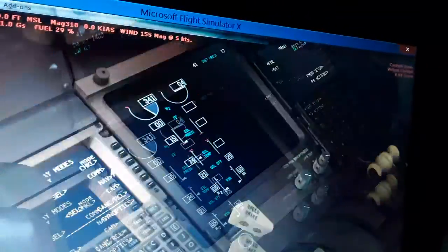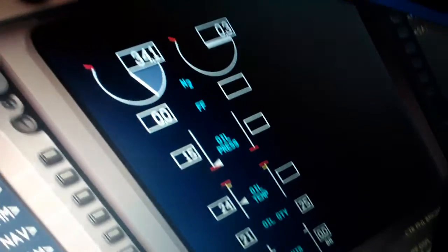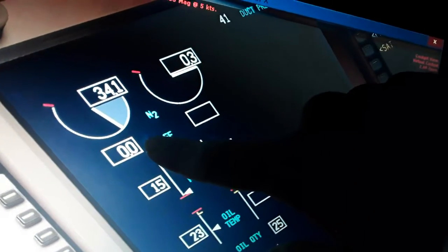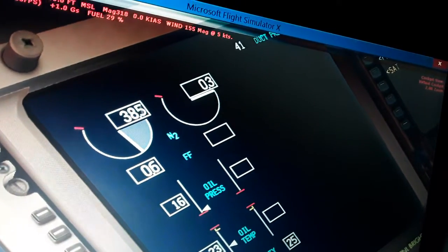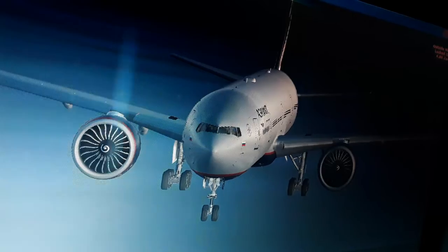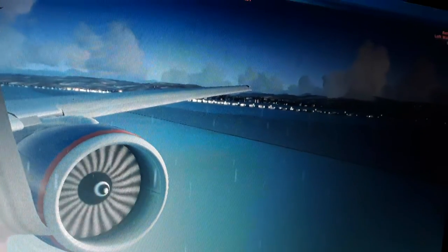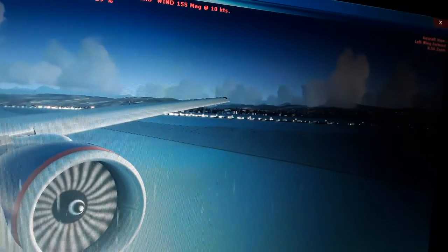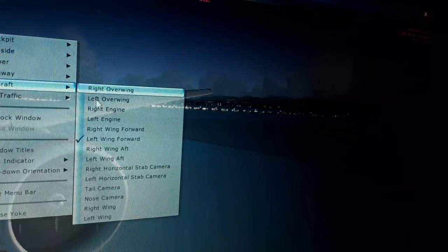So we can let the fuel now into the left engine. We have enough compressed air in the engine starter. So you're gonna see the fuel flow now, here from 0 to the left engine, going up 0.5. So we come here outside, you're gonna see the engine spinning more rapidly now. Here we have the engine start, this engine. Now it's fully working. So we're going to the other side engine now.